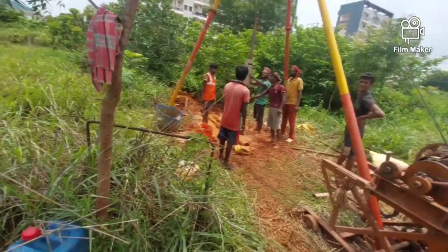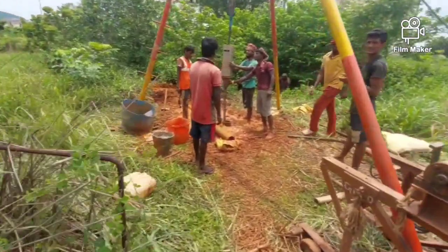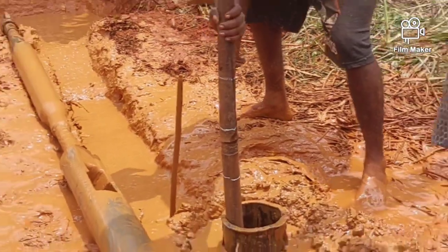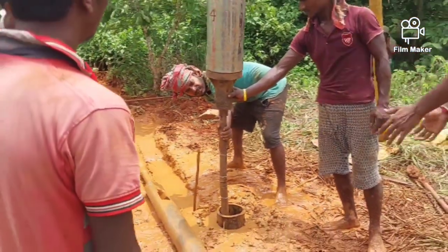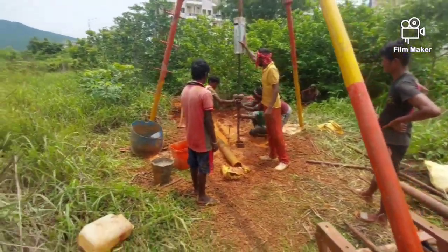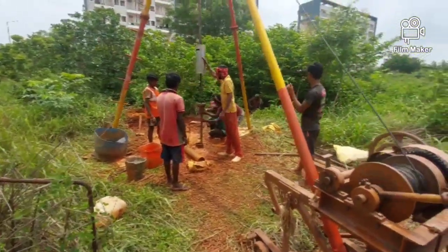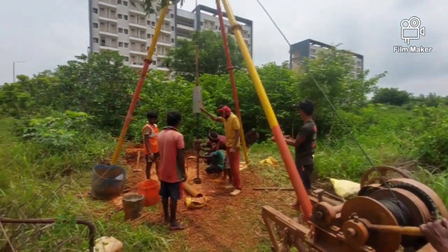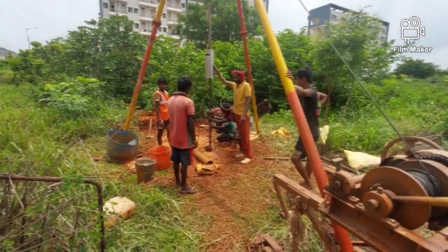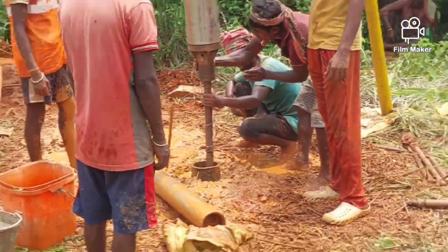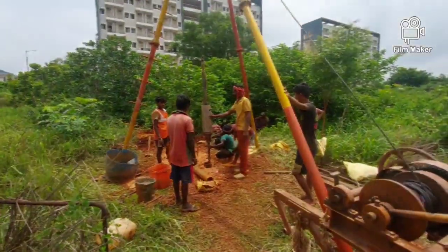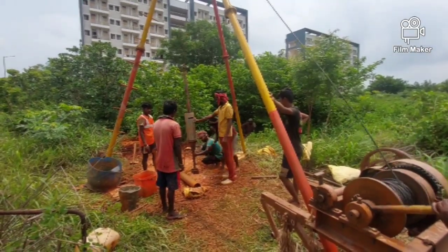Here the hammering will be done, and the blows for the first 150 mm are not counted, as it is the seating value. After 150 mm it will be counted. Here the hammer free falls from 760 mm by auto tripping. You are only pulling the hammer, but the hammer falls automatically. There is some spring connected. So the hammer drives this rod and split spoon sampler into the ground,